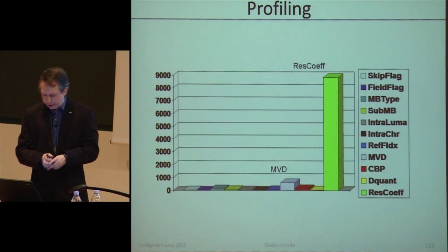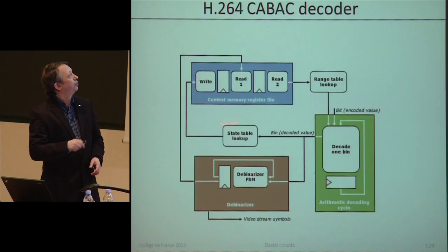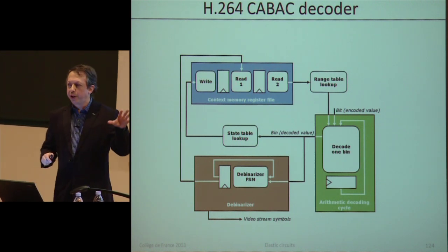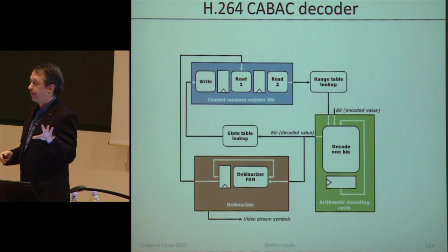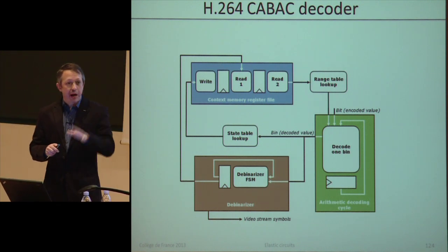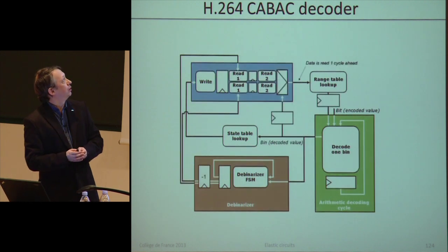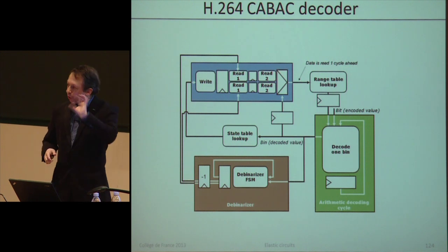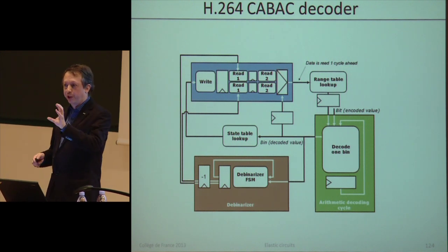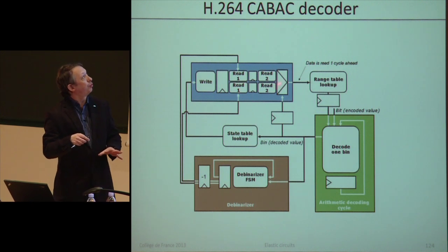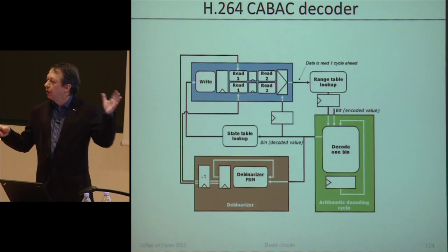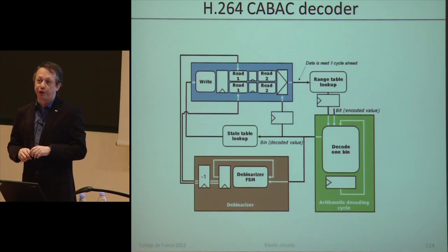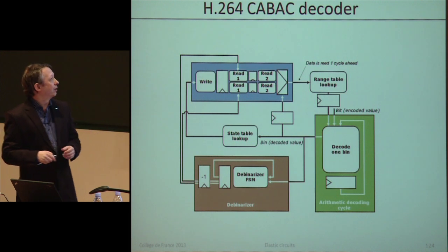And the problem here is that when you design this component, for example, the critical path is determined mostly by those operations that are not executed very often. So what they did is just to optimize for the most often operation, and they did one circuit, the read 1 and read 2, for the most frequent operation. That was a fast combinational logic, while the other read 1 and read 2 at the bottom was for the most exotic operations, the not so frequent operations. It will take more cycles, okay?